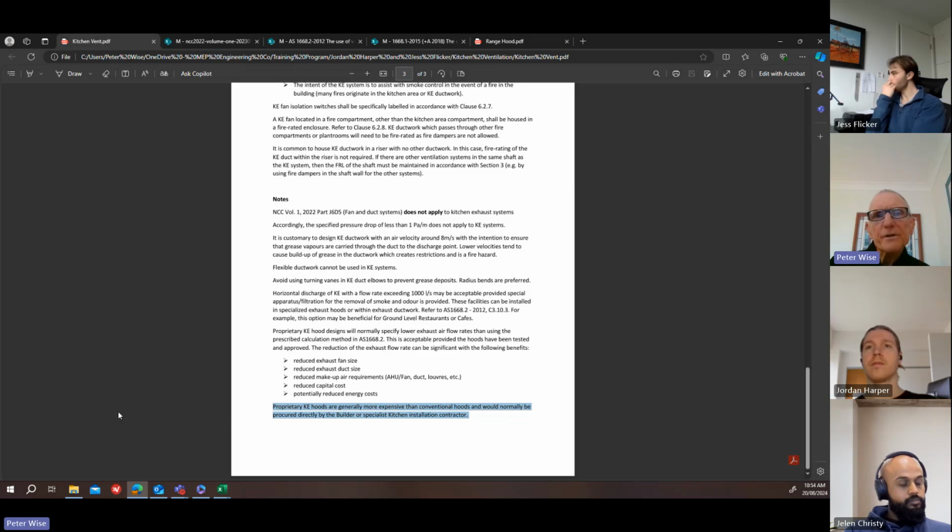Go to AS 1668 Part 2, find that cooking process, have a look at the appendix, what sort of hood do we use, do the calculations. They're not difficult, but it's just a process you need to go through. Unless there's a proprietary hood being provided, then you need to get the details and work to that. Any questions?